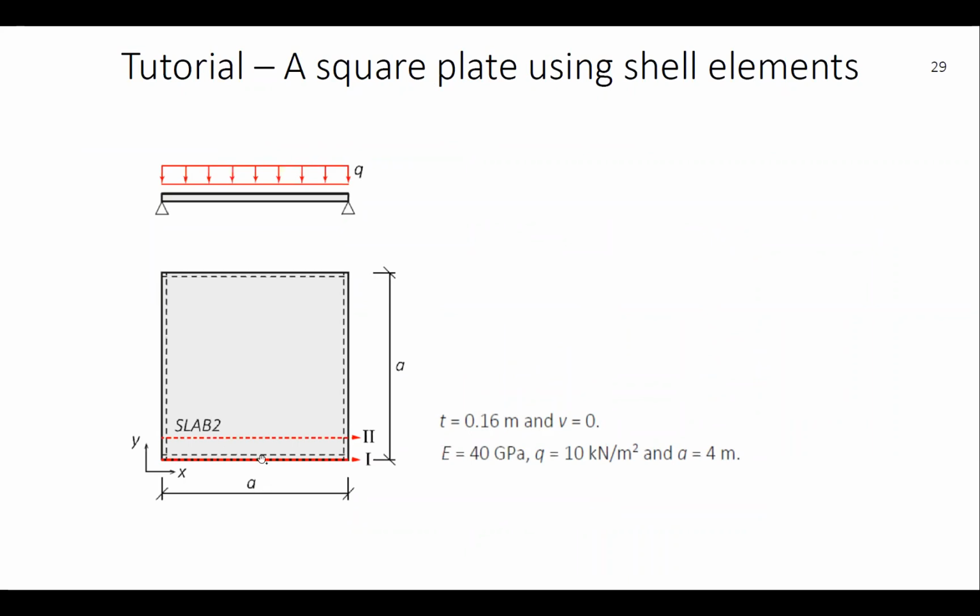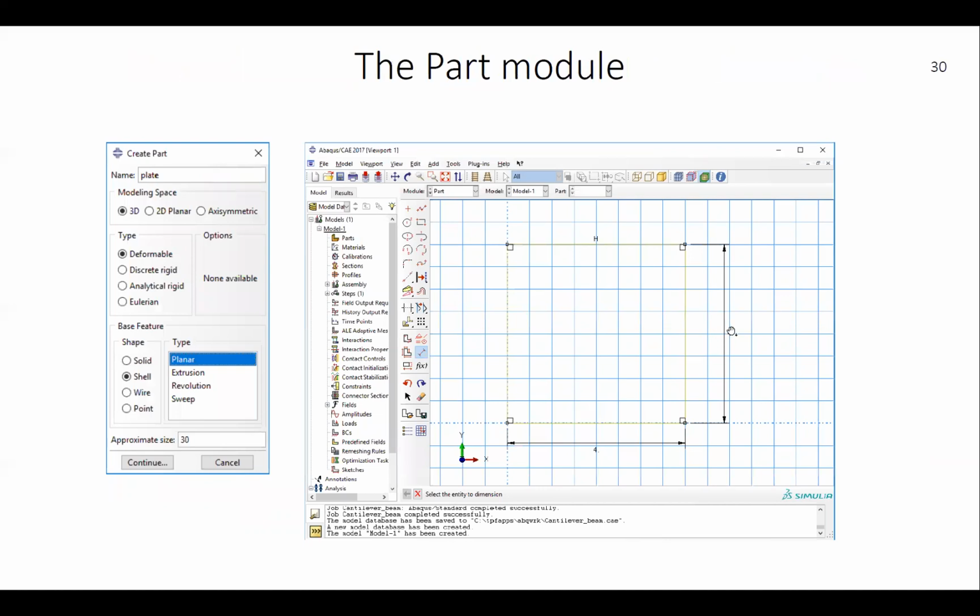So this is actually the same slab that you will have in part of exercise A. In this case, let's see what boundary conditions here. It seems that you have simply supported on 4 edges, so slab number B. Let's see if it was the one I analyzed. Same procedure as for the plane element. For the cantilever beams, you make the model in the part module.